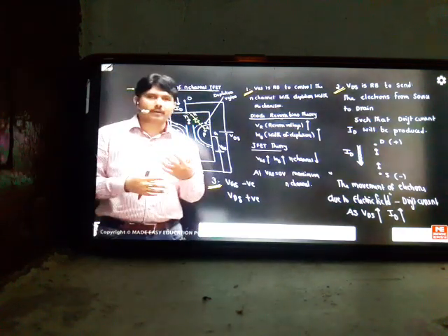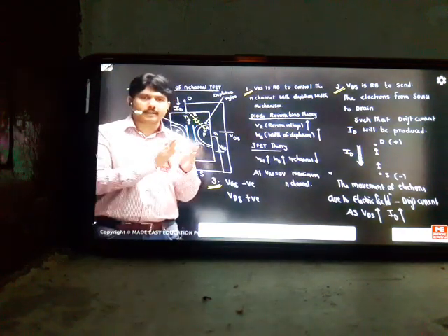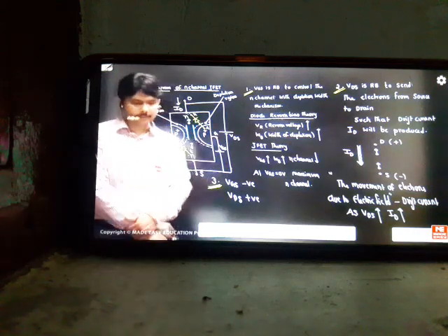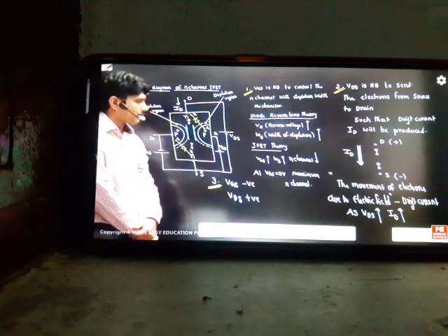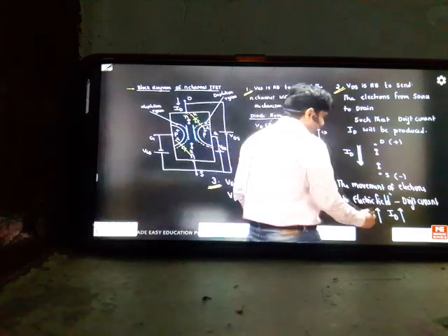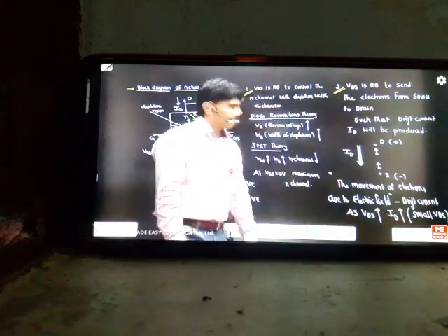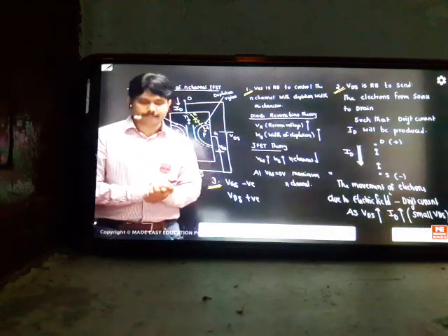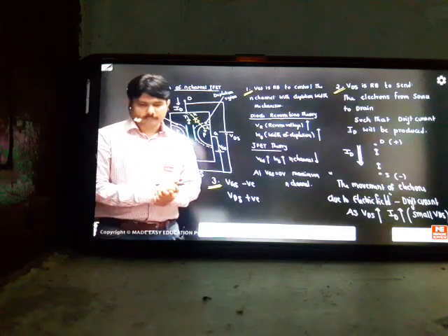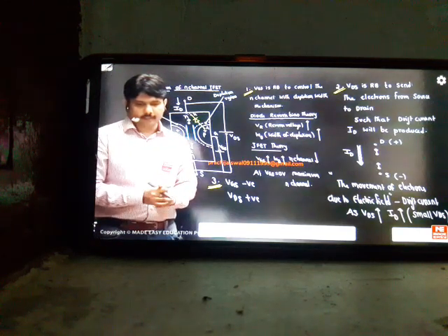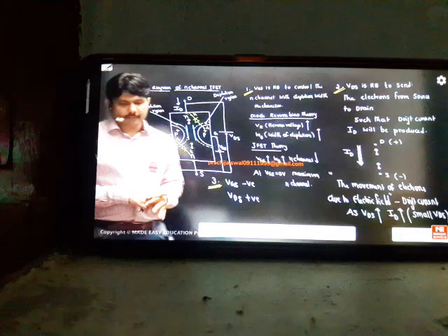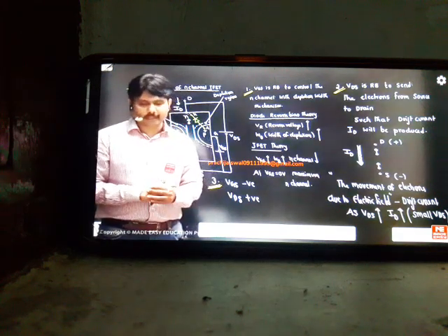As the electric field increases, the current goes on increasing. At that time, the behavior will change. I'm telling you, in the first initial case, as VDS increases, ID will increase. Okay. And this condition is good for small VDS values, not for large VDS values. If you want, you can write it. If you go for large VDS, it will change again. Yes, sir. Divyadas, the statement you said is wonderful, correct. We need less VGS, we need more VDS to give the high current.